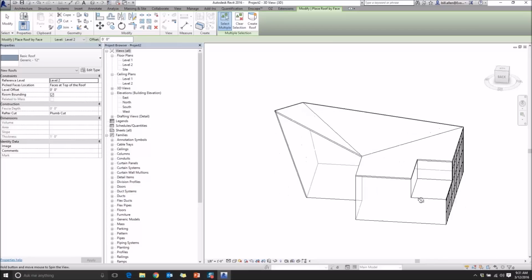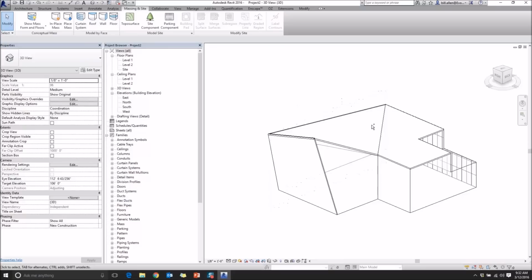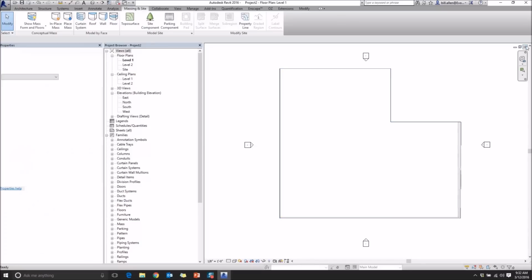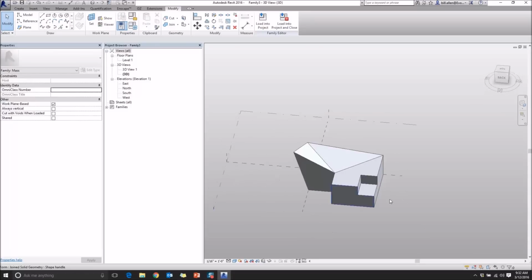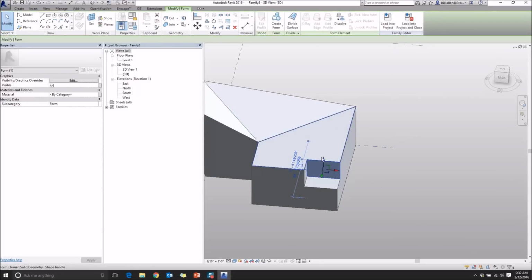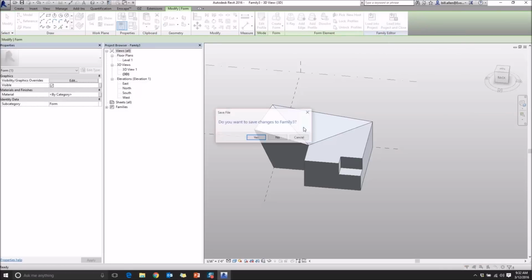So the other thing, let's say that your designer's designing in Revit, the conceptual mass, you're going to hear hosting walls, and then they go ahead and update the design, as it always happens. So you don't have to lose that information. I'm going to just kind of simulate how that would work. So let's say that maybe programmatically, they needed a little more square feet, so they're pushing this out a little bit, and maybe they don't like this move here, so we're gonna pull this down a little bit, and then we'll load that back into our project. No, I don't want to save that right now.